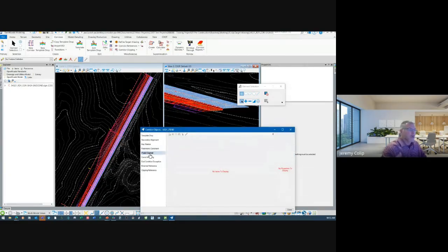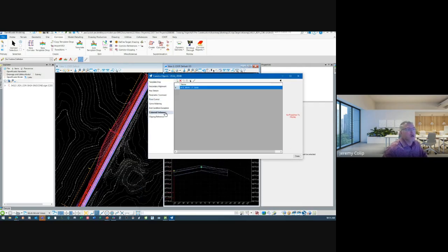One reason too: right now I have 0 point controls because I'm controlling through alignments and through features. With point controls, the more you have, and I believe the number is around 20, once you get past 20 point controls, your corridor and your processing time will start to slow down. The more you get, the slower it gets. I would not ever go past 30. If you go past 30, you're probably going to have problems. It's probably going to crash. This is another reason to do this.